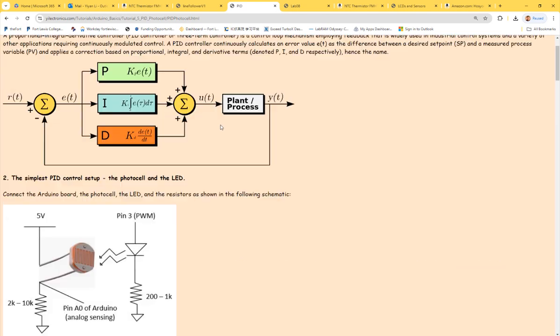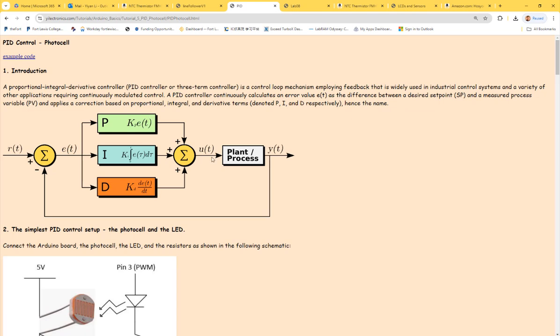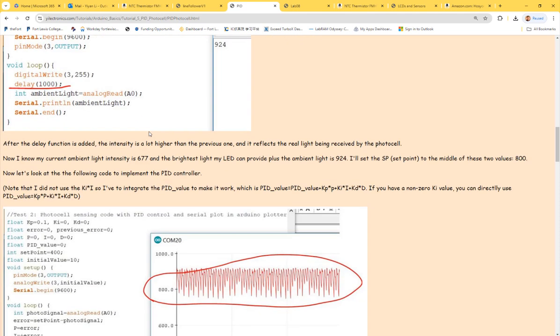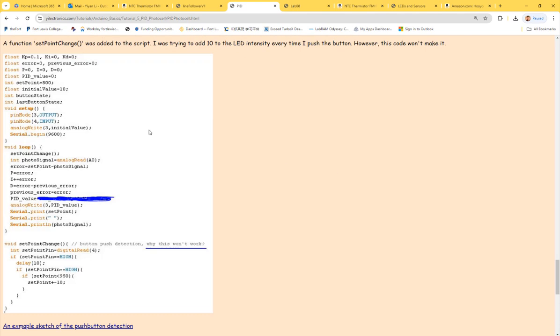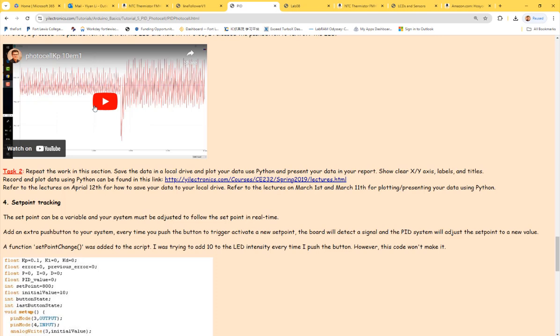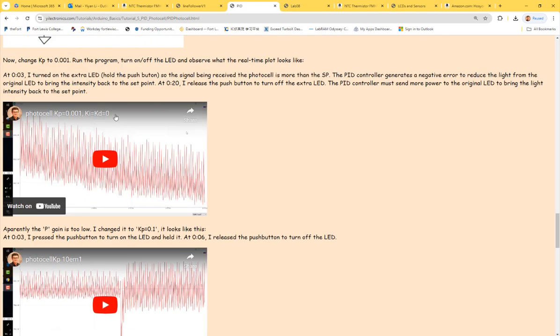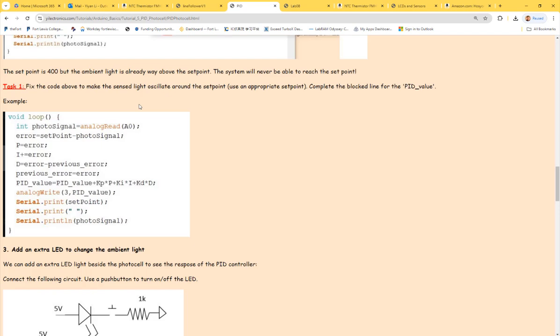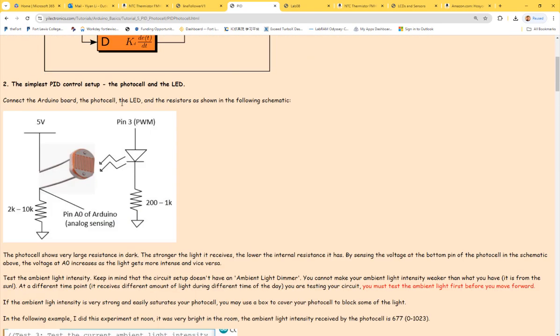If you want to work on this one, just get the equations implemented in the C code. It's not really long. You can see the Arduino ones. It's the same C code. It's not long at all. That's it. That's a PID controller. You can implement it and use it for LED brightness control. Think about it really quick, how that works.